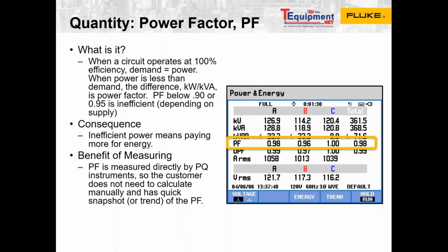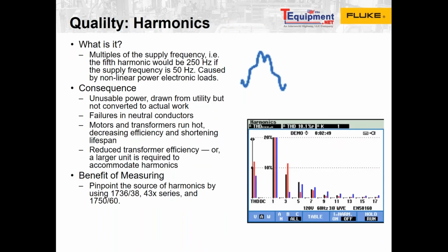I know a lot of people use digital multimeters and they'll measure each phase one after the other. And they'll do a bunch of calculations, right? Pencil and paper calculations or Excel spreadsheet calculations to figure out their power factor. The nice thing about the Fluke power quality tools is it does it for you. And it does it in a way that makes more sense. It'll measure all 3 phases at the same time and your neutral at the same time. And yeah, that's enough about power factor.